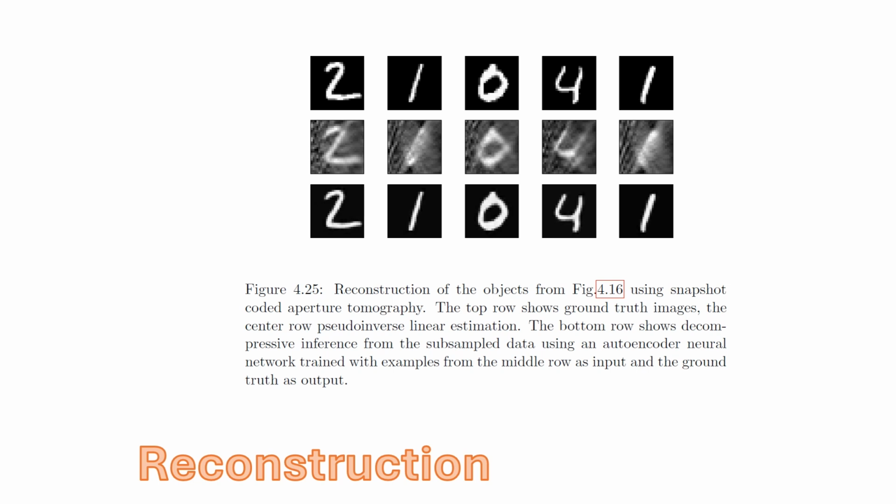In the real examples, you would use the code and the design in an iterative form to try to optimize overall system performance, and you may be interested in things like orthogonality of codes as with the harmonic or mirror codes and other sorts of non-algorithmic ways to evaluate the quality of the codes, including looking at the structure of the singular vectors. So that's an example of coded aperture imaging.